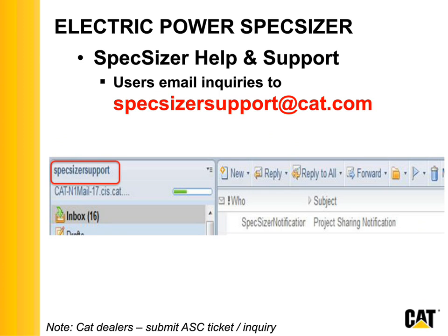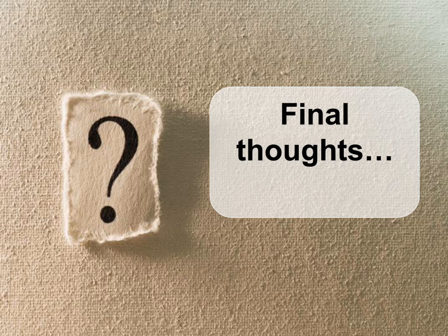Steve, that's a lot of great information. But as we end our session today, what are the most important points to take away? Yeah, Mary, that's a really good question. There are a few things that I'd just like to briefly cover again before we end here. Number one, always check the optimizer. I've worked thousands of inquiries over 10 years. 30 to 35% of the time, the size genset could be reduced just by running the optimizer. If it moves a load in a step that you don't want it to be in, you can always manually move that load to another step, then resize your genset.